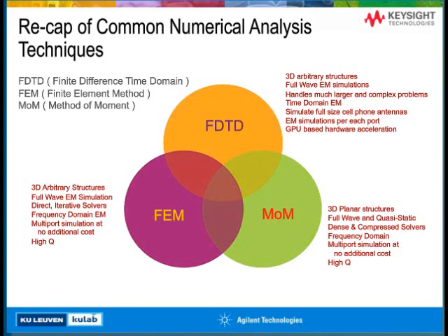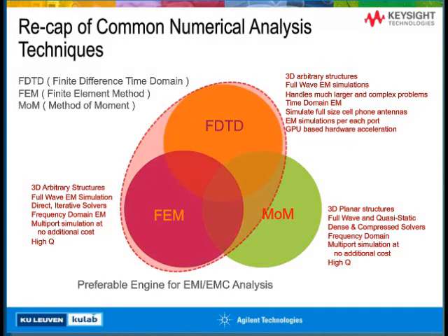However, speaking of EMI EMC problems, due to the complexity of the problems and their 3D nature, full-wave EM solvers, which are FEM and FDTD, are the preferred EM simulation technologies for dealing with EMI EMC problems.